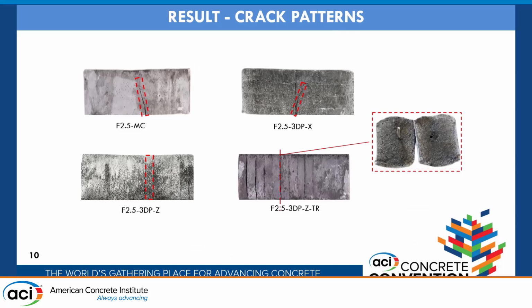And just to provide some information on the crack pattern, as opposed to the plain mixtures with no reinforcement, which have shown a brittle behavior, the modcast and 3D printed specimen showed flexural shear failure, while the Z direction specimen also sheared along the interface. And by adding the extra threaded reinforcement, this failure mode wasn't observed. But by closely examining, we saw that there was a bond failure between the threaded reinforcement and the fiber reinforced matrix.